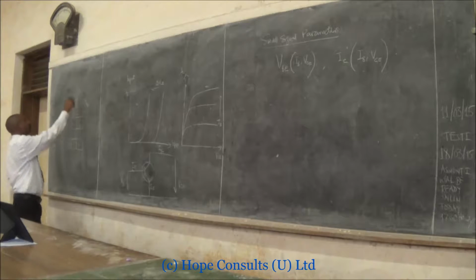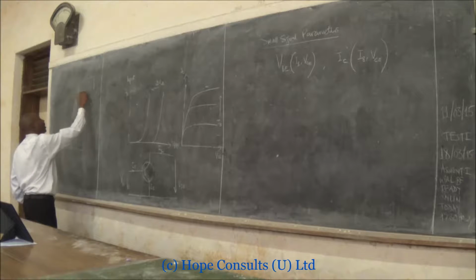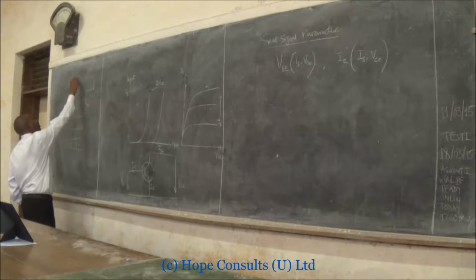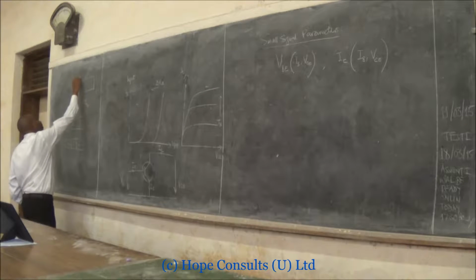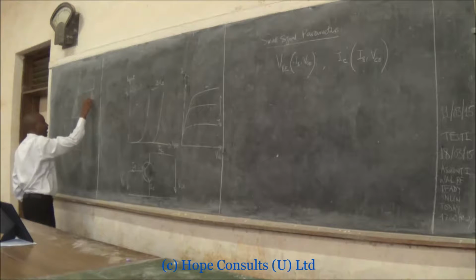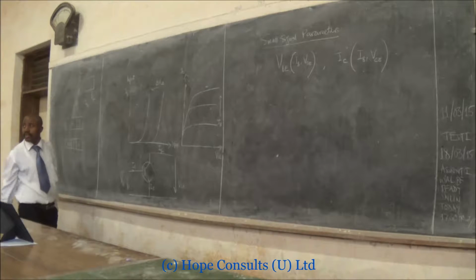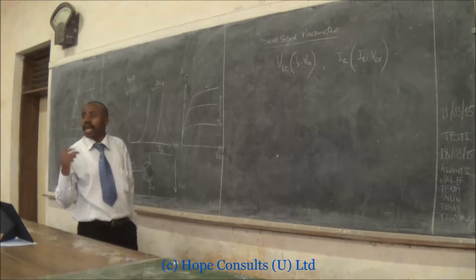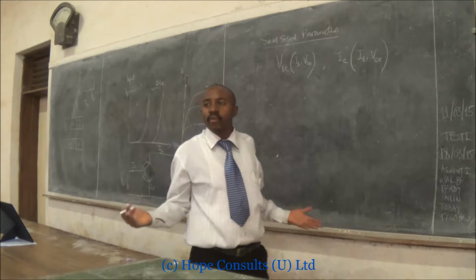Just like when those of you who have done the experiment with the chips, when you supply it, you have to make sure that you have VCC here and you have your grounding here, for the chip to be active. Otherwise, it won't give you anything.